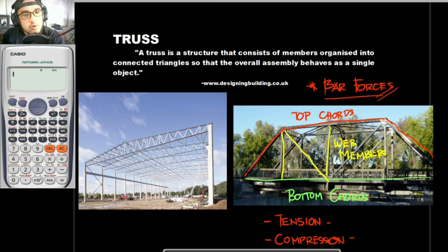Trusses are most commonly used in bridges, roofs, towers, and so on. The example to your left is a roof truss. For example, you would be installing your roofing materials there, and of course, your roofing materials have corresponding weights. Its weight would be transferred to the truss, and in the truss itself, all of these members would have certain bar forces. So may it be tension or compression, the loads would be distributed to these bar forces to make your structure stable.